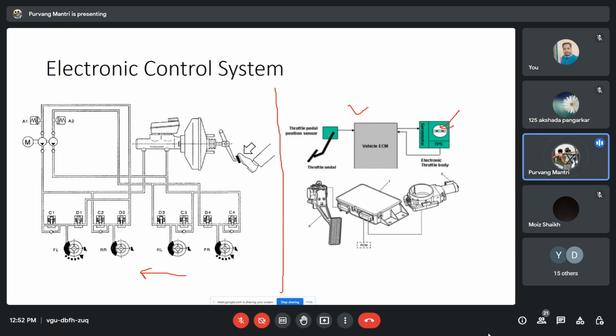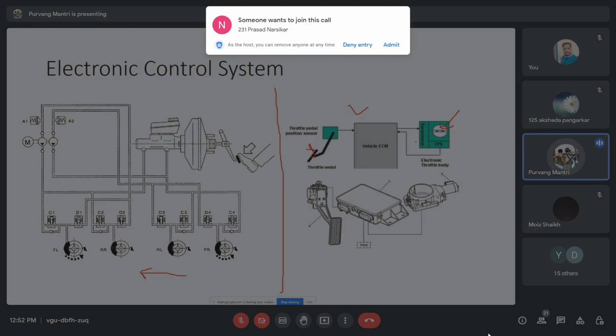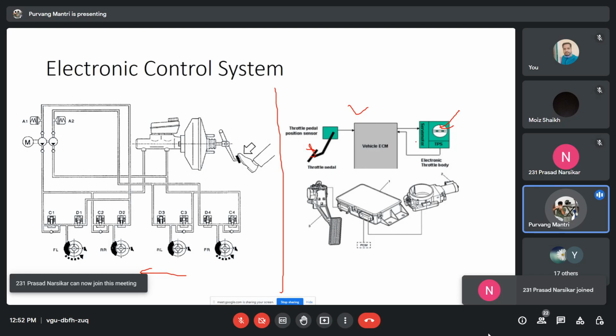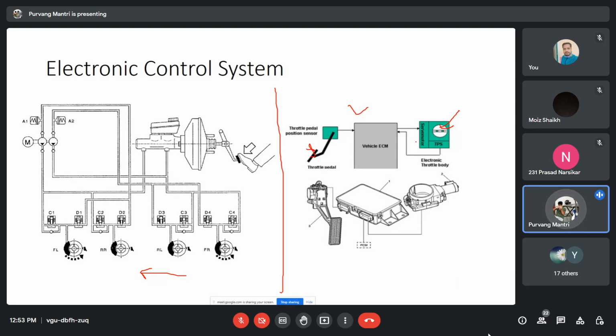So as you press the throttle pedal, the position sensor is going to give data to the microcontroller, and it is going to signal the servo motor to rotate in that particular direction. This might be difficult to imagine at this point. So don't worry. I have created a small simulation for you guys to understand. I have attached a potentiometer with an Arduino, and it controls the servo motor. So I'm gonna show it to you how this kind of system works.